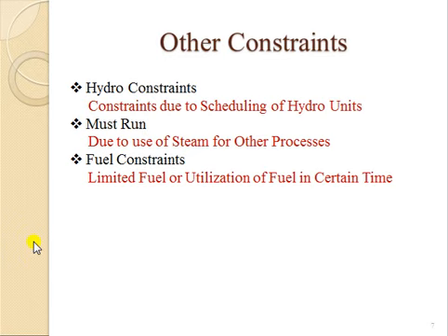Now, the majority of the constraints are for thermal power plants, but when you are considering other technologies like hydro, you are aware hydro's entire operation depends upon the availability of water. The same water we are using for agriculture, the same water which we are using for domestic purposes also. So there are some constraints on hydro units, on how you can schedule those. Though they are fast responding, the scheduling of hydro units is somewhat complex, and that constraint you have to consider in this unit commitment.